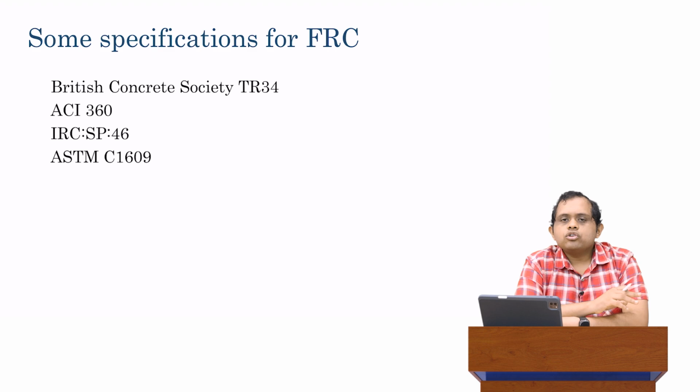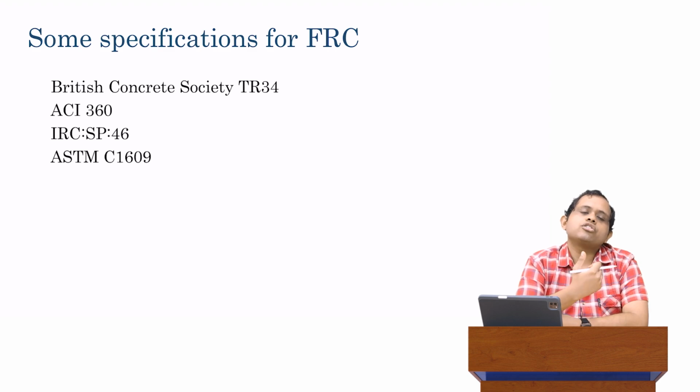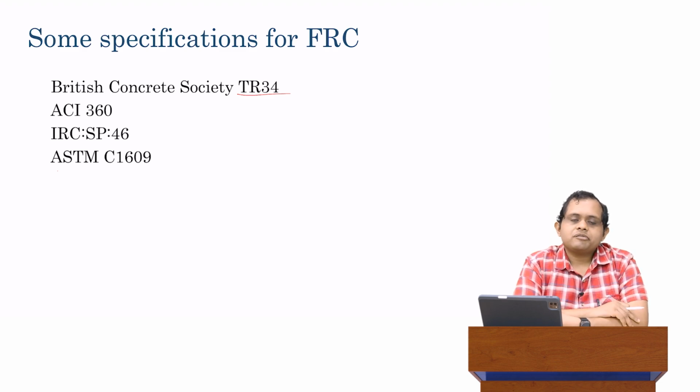So here are certain codes which you will find if you just open up a search engine and try to look for standard codes for FRC; you will find a number of them. One of them is the British Concrete Society's TR34, that's Technical Report number 34. ACI, the American Concrete Institute, has their specification number 360, which is for FRC. IRC SP 46, which I've already talked about, Special Publication 46 in India, which is for FRC.